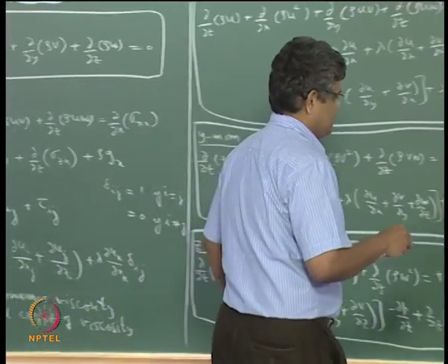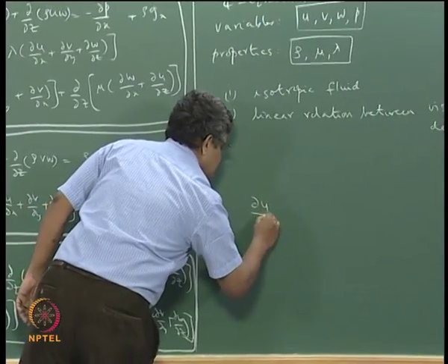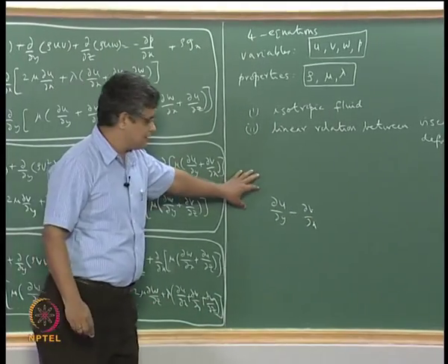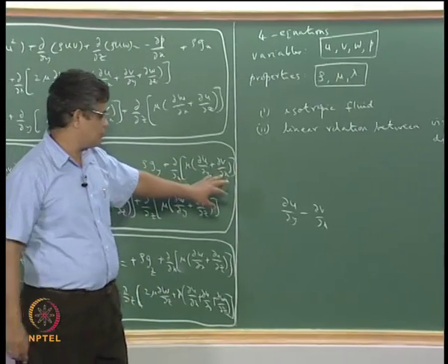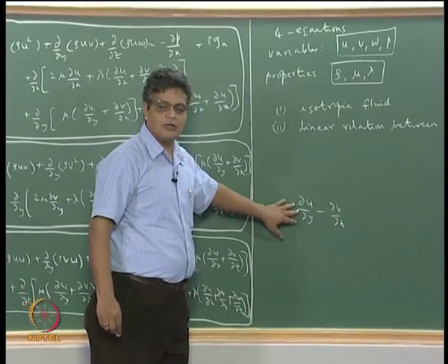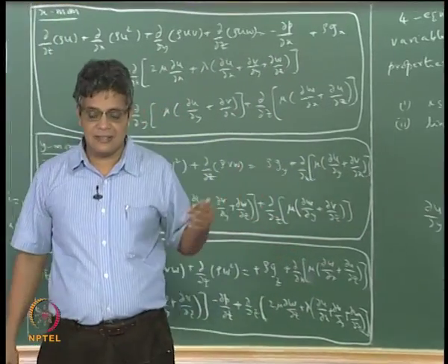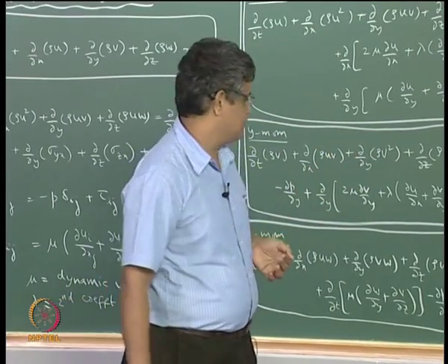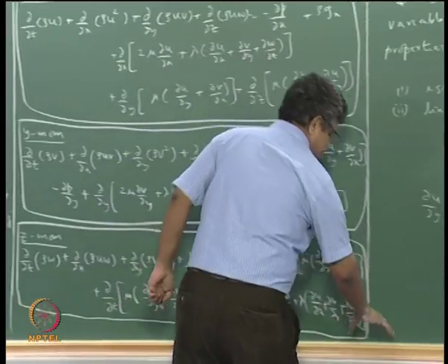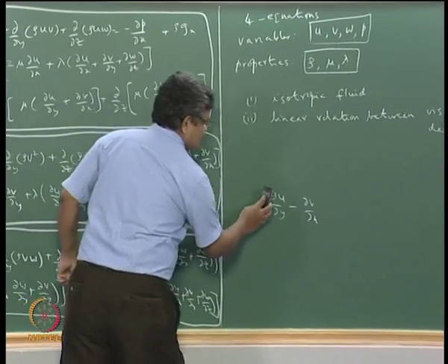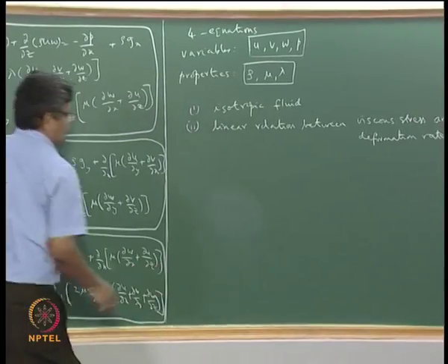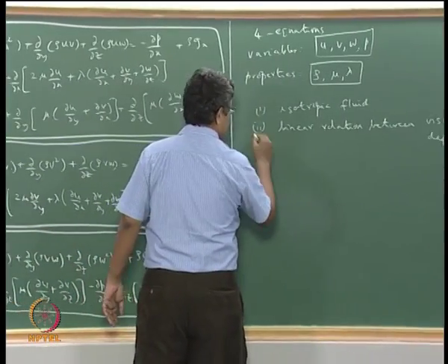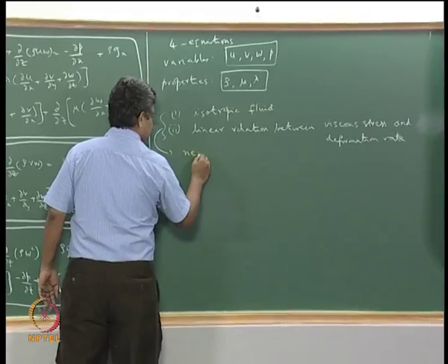in terms of, for example, ∂u/∂y minus ∂v/∂x. In terms like this, when you have a pure solid body rotation, there is a corresponding non-zero strain rate, so there is a corresponding relative motion, but we say that that is not causing any stress. That comes as an inbuilt package of the frame invariance of the relation. So under these conditions, those fluids which satisfy these conditions are called Newtonian fluids,